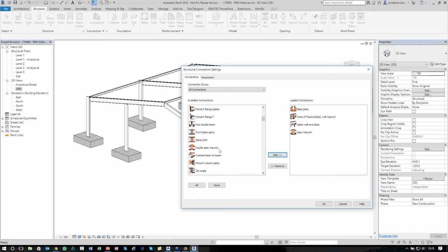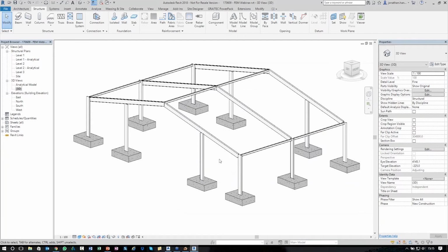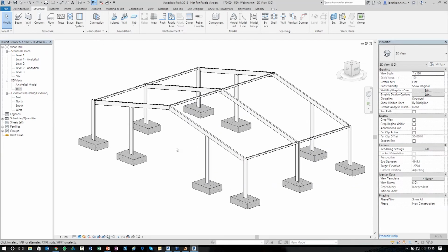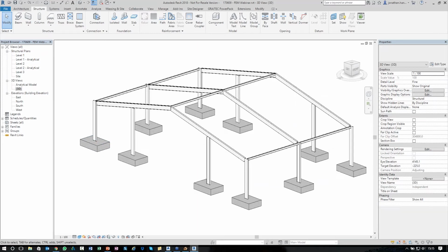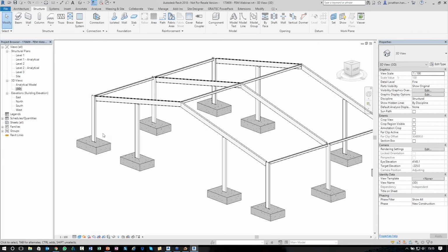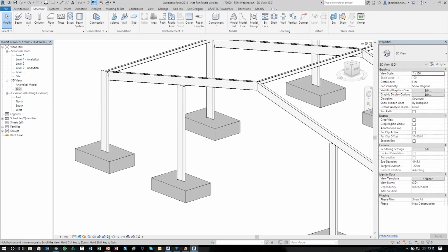So part of this is connecting the workflow to the structural fabrication, and again, taking your Revit model into structural intent drawings where an engineer would show complete connection detailing. So it's really quite simple to use. You select your structural element, go to the Structure tab, click Connection, and that will go in and apply a structural connection node. It's got a generic connection, and then you just specify which connection you need.